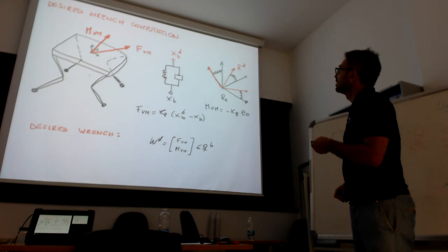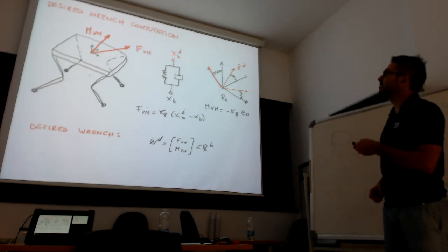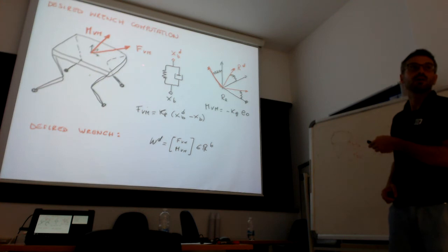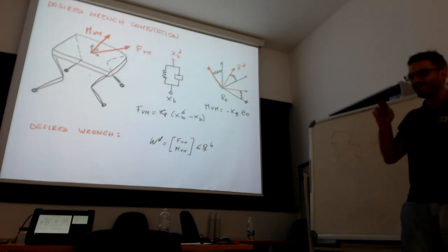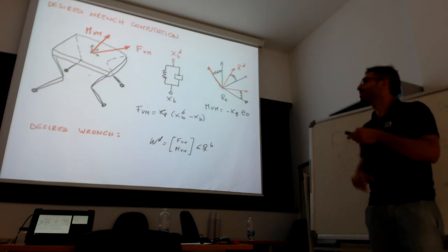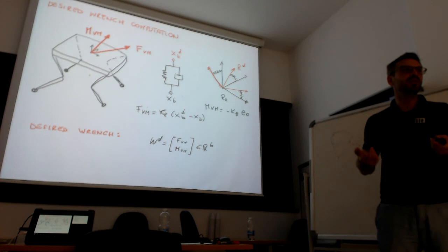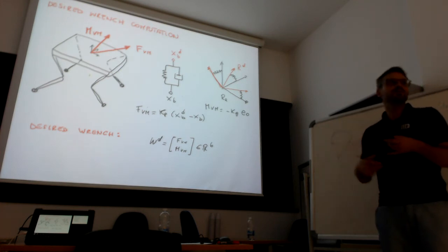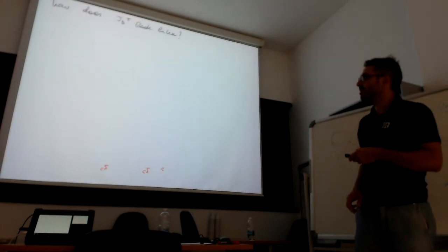Here. This is actual COM or actual base position. This is desired base position, and this tries to eliminate the error. Okay. So I agree. The feedback controller, in a sense, is the very first step. Compute the virtual impedance. Then you have the mapping to contact forces, and the third step is mapping to torque. Good observation. Yes, it was not clear.